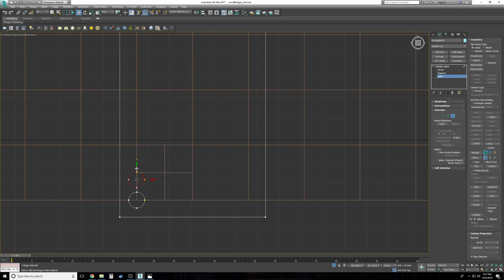But you can do what I just did, because I held down Shift and just made a copy of it. It's just right there, and it's still part of the whole entity. It's what I was telling you earlier. Move this around and it's still one piece. So you take this piece and align it back to this square. But you don't want the X because you want it to stay right there. You just want it up here because we're all on 1 inch areas. Make sure it's the Y, make sure it's maximum because we're on the top, not the bottom this time.